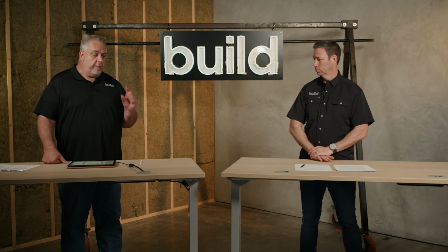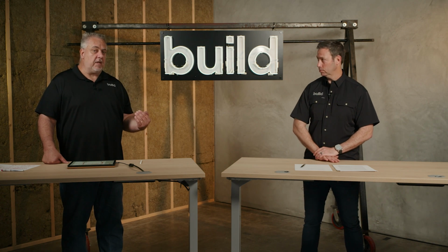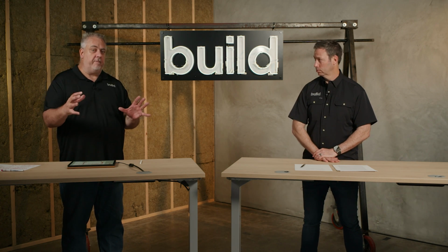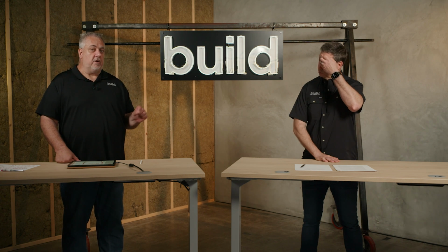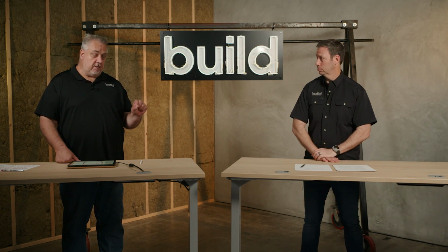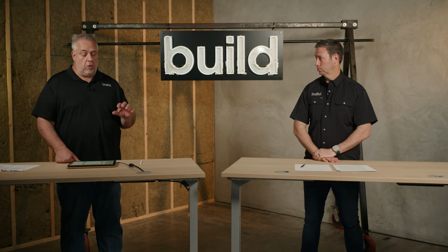And if you watch some of the earlier versions, I'm not a big fan of labels. But what I am the biggest fan of is discussion. And when Passive House came to the U.S., there's this set of building metrics. One of their metrics was air tightness, and it's 0.60 ACH, air changes per hour, at 50 pascals.